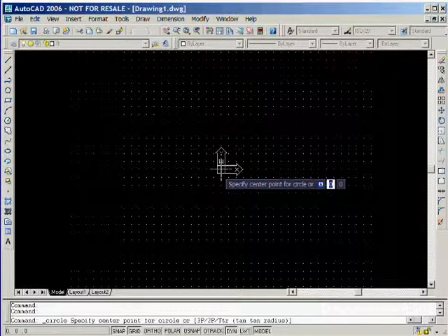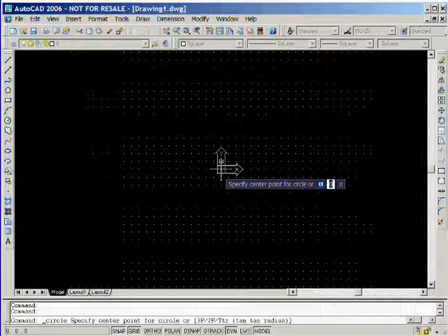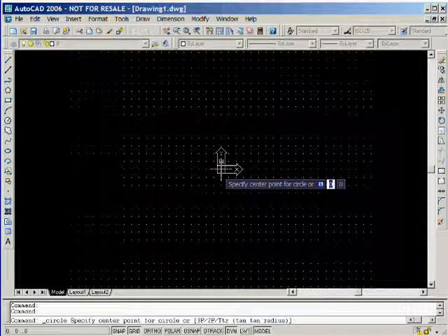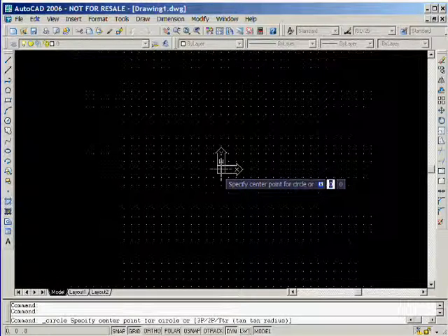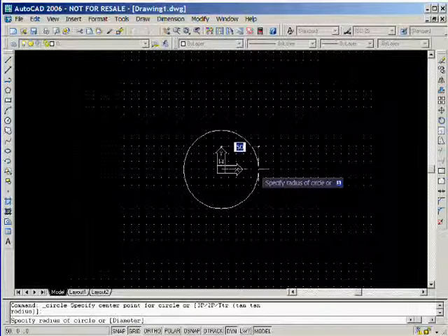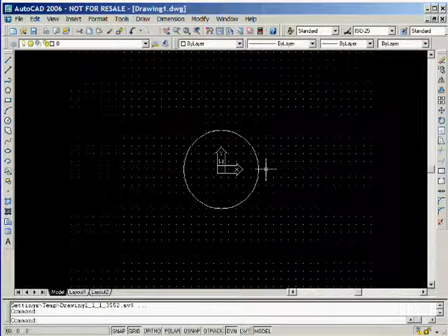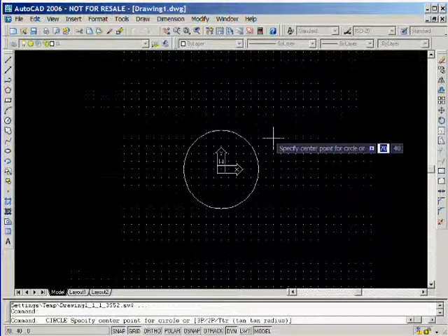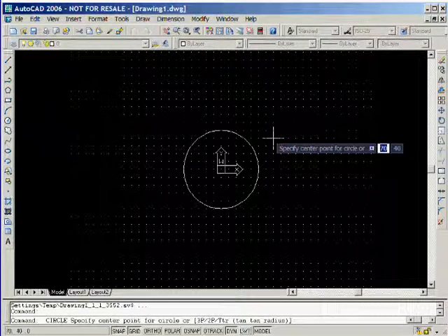We are now ready to begin drawing several circles, which we'll start to do by clicking on the circle icon in the drawing toolbar. We'll next place the center of the first circle at the origin of the coordinate system by clicking on this location and then moving the crosshairs to the right until a value of 50 is displayed to define its radius.